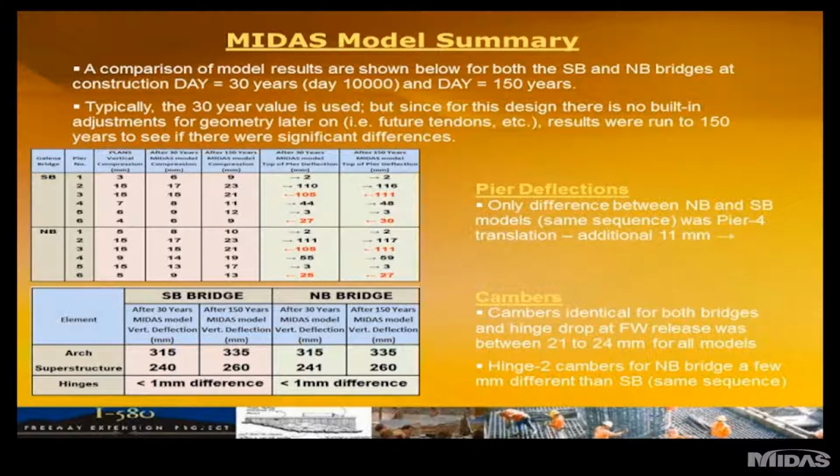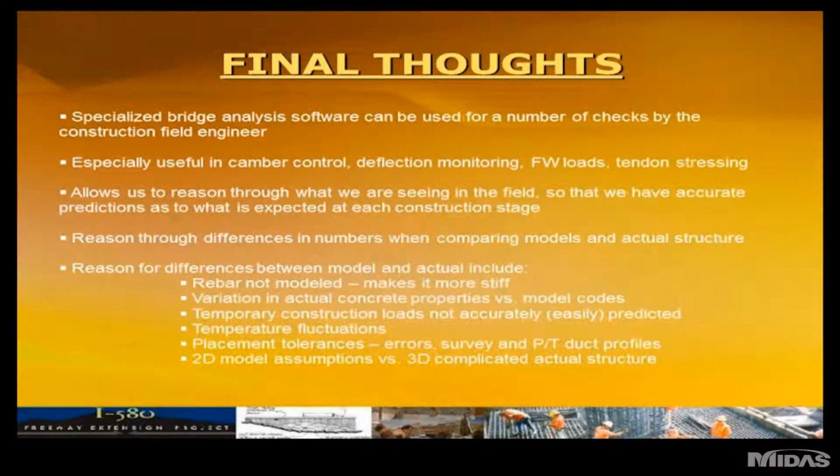I'm going to wrap up with some final thoughts. Obviously, specialized bridge software can be used for a number of checks by the construction field engineer. It was very useful in this particular instance for camber control, deflection monitoring, modeling of false work and temporary loads, and tendon stressing.